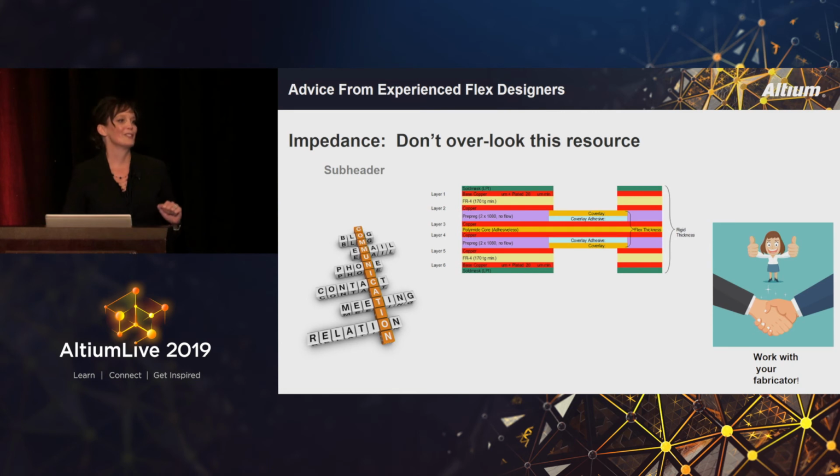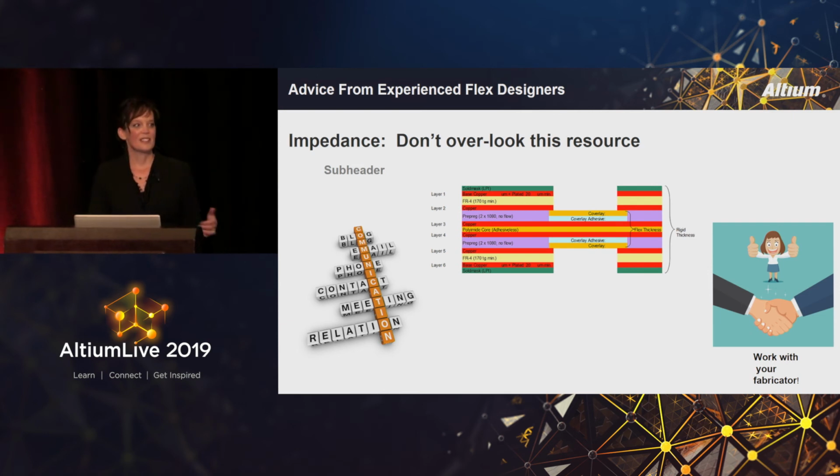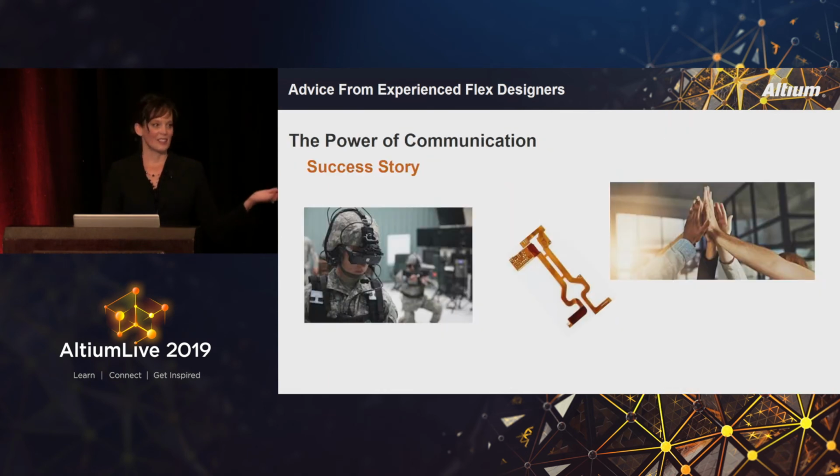And then don't overlook the resource for impedance with your fabricator. So there's a lot of tools out there to help you anticipate impedance and work through your stack-ups. But fabricators' tools are a little more sophisticated, and they're constantly adding the results from all of the materials and designs that they build into that, so it can be a little more precise. And I'm always going to recommend to use your fabricator for a stack-up. So if you have impedance requirements and things like that, it's a great resource.